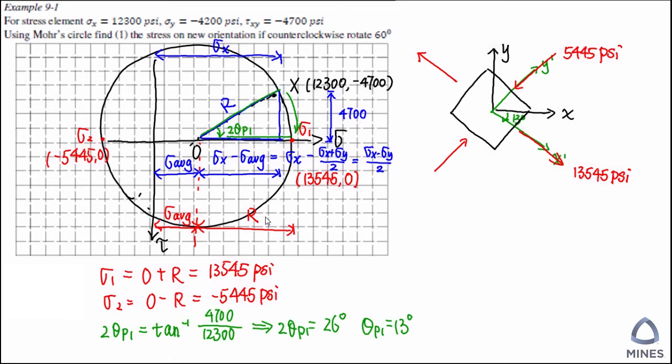So now what we are going to do is actually draw what is the maximal shear stress. For this maximal shear stress, we can see the point, I just marked here, is actually going to have the maximal shear stress, which is the radius. However, the normal stress at this point here is not going to be 0. It's actually going to be the center of the Mohr circle.